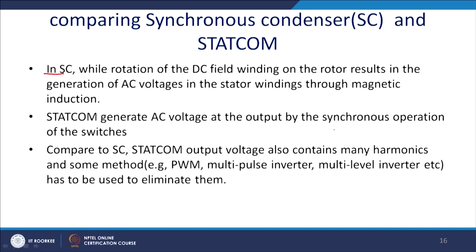Compared to SVC, the Statcom output voltage also contains many harmonics, mainly switching harmonics. But please understand that the power system is a low pass filter, so the switching harmonics will automatically mitigate, or you can put in a low pass filter. So, ultimately those harmonics will sink,